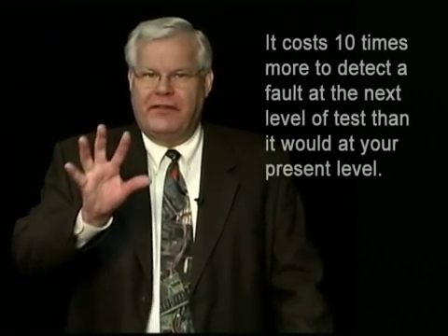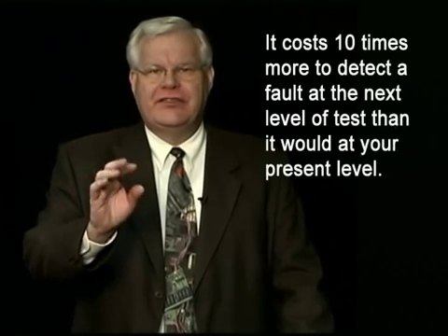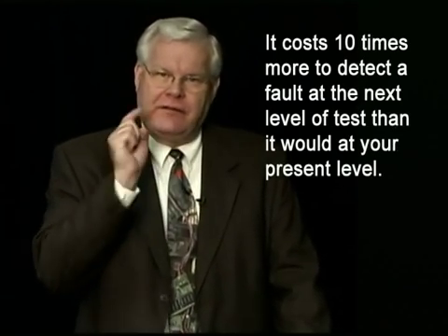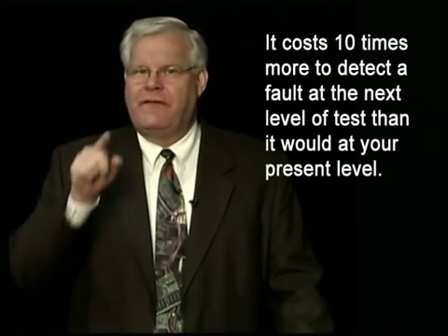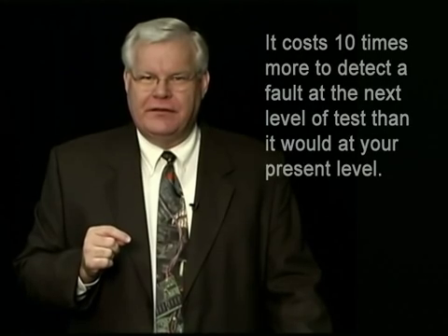But let's just assume for the moment that the generic formula of the 10x theory holds, and the 10x theory is just saying that if it costs X to find a fault at ICT, it would cost 10 times that, 10x, to find the same fault at functional test. And if I had to find the fault at unit test, it would cost 100 times as much. So I can't tell you how many times I've gone into a factory to help somebody with functional test or in-circuit test, and they say, oh, we don't worry about catching those kind of faults at ICT because functional catches it. It costs 10 times more.